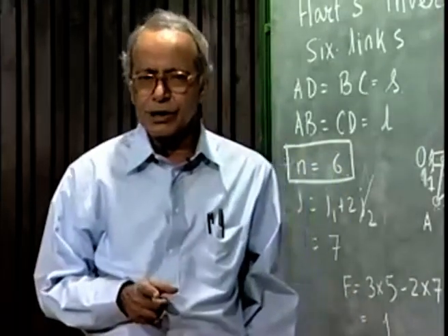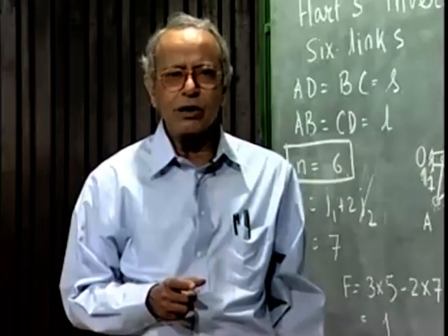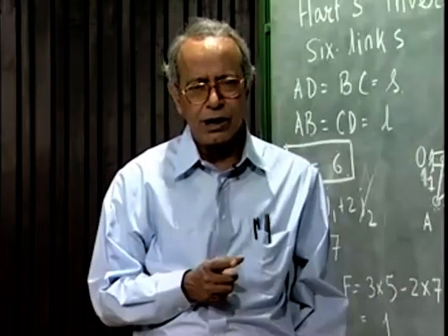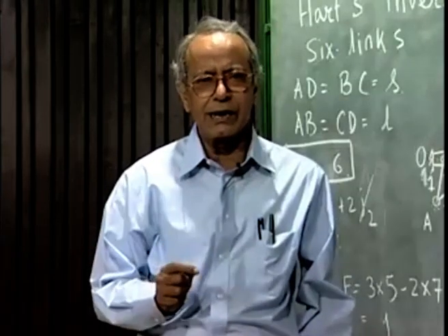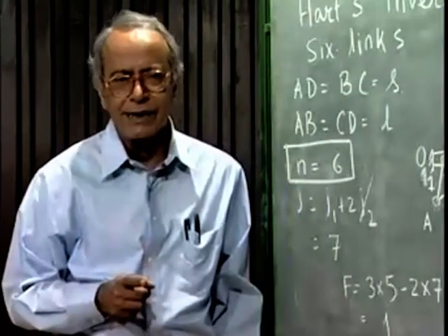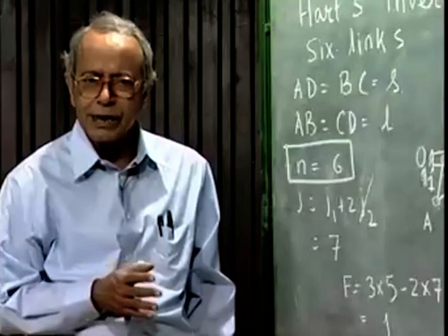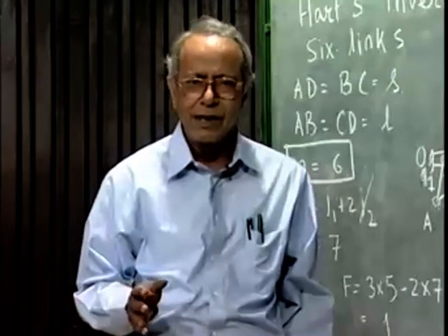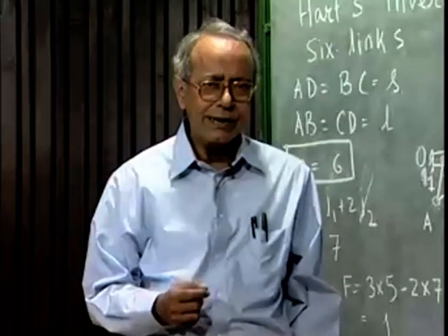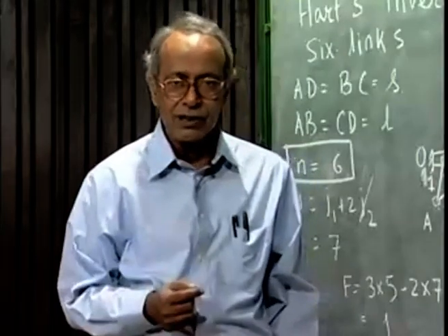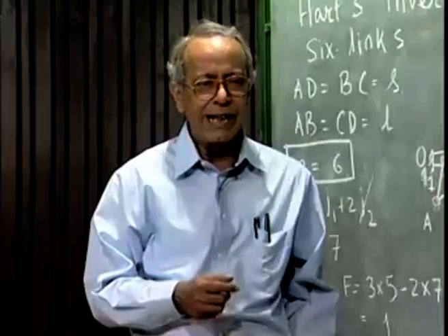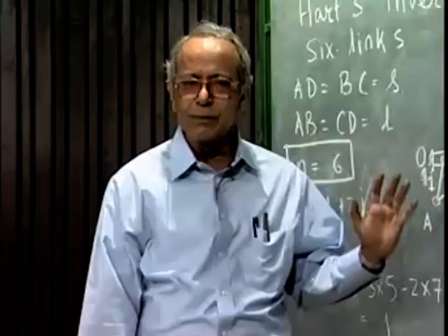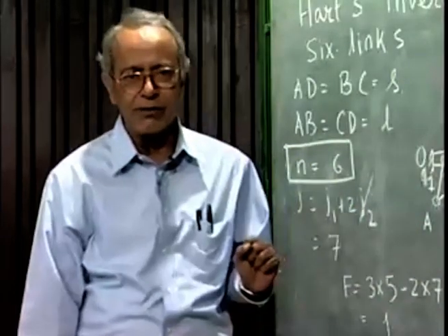In such a situation, if we take a point on the extension of the connecting rod suitably, then we found that that point on the connecting rod generates an exact straight line perpendicular to the direction of sliding of the slider. After that, we discussed the principle of inversion, and I would like to emphasize again that you should not confuse this principle of inversion with kinematic inversion.